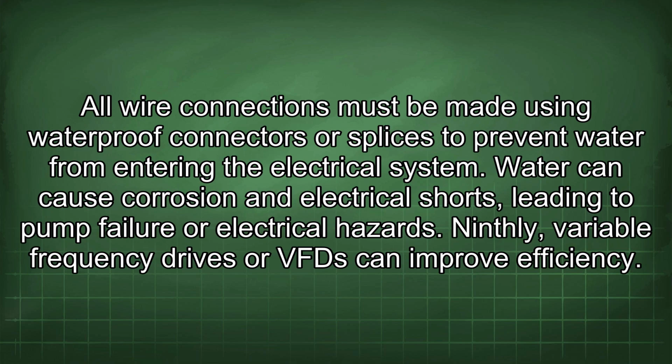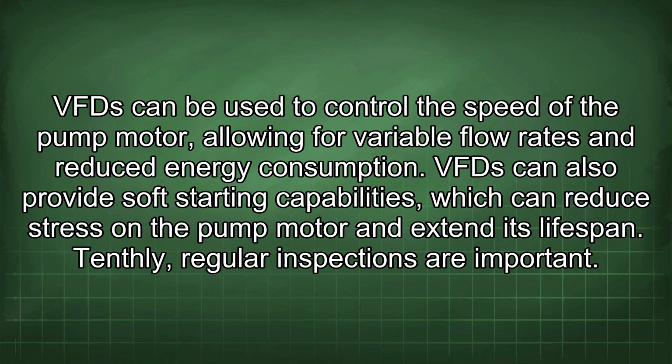Water can cause corrosion and electrical shorts, leading to pump failure or electrical hazards. Ninthly, variable frequency drives, or VFD, can improve efficiency. VFD can be used to control the speed of the pump motor, allowing for variable flow rates and reduced energy consumption. VFD can also provide soft starting capabilities, which can reduce stress on the pump motor and extend its lifespan.